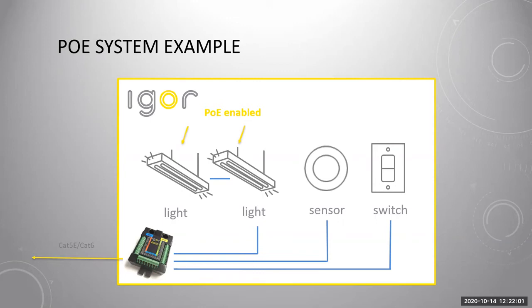We don't have a dry contact built into the nodes. Typically, we would utilize an external relay with, say, a 24-volt DC coil. We do have relay control outputs, but they're designed for just a small amperage, just enough to run that relay coil. For certain instances, like plug load control or controlling line voltage motorized shades, we would do relay control via external relays, such as a Functional Devices relay in a box. We've used those a number of times for that application.